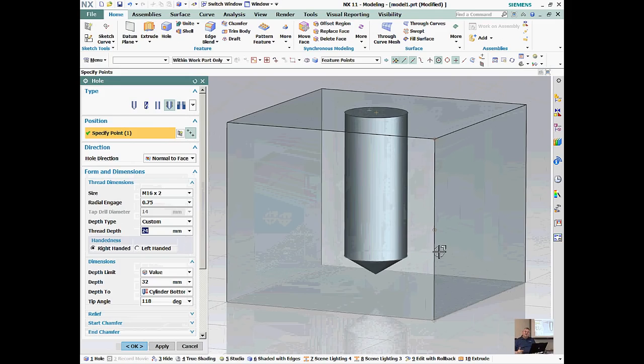But as designers, sometimes it's very important for us to know where the actual end of the hole is, because it might be part of a manifold or something where it's confined to a very small area, and you don't want that drill tip to break through the model. So you would really like to control the depth of the hole based on that tip length. But we've never given you that ability in the past. You'd have to work it out for yourself.